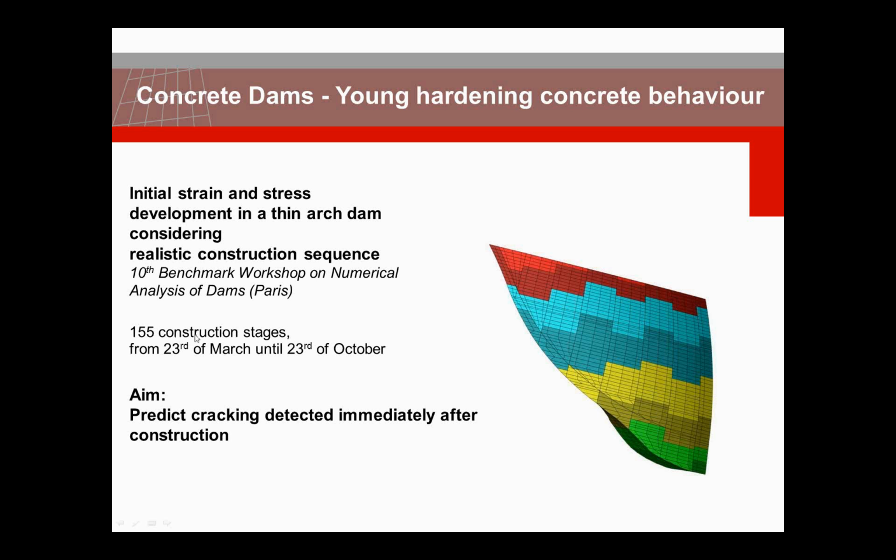It's a stage construction analysis of an arch dam in which we want to look for the reasons to predict the cracking immediately after construction. So not cracks as a result of the hydrostatic loading of the dam, but just from the hardening of the concrete in the initial phase.